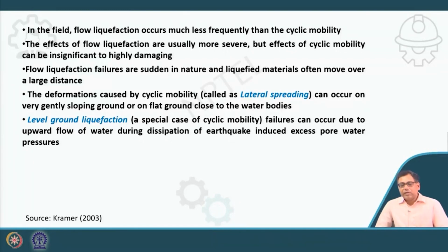Clear? So in summary, in flow liquefaction the deformation is driven by the static shear stress, and the shear strength of the liquefied soil is less than the static shear stress of the soil.